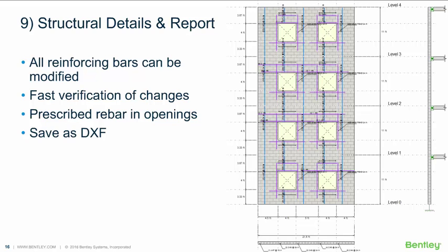Your step number 9 would be, after specifying those masonry parameters that we discussed in the previous slide, the software will design the wall for you. There might be some cases where the software is not successful optimizing the wall. For example, when not even the maximum area of steel produced by the bars you specified satisfies the nominal moment. In this case, you would have to either increase the bar sizes to be used in the process or increase the wall thickness, maybe.